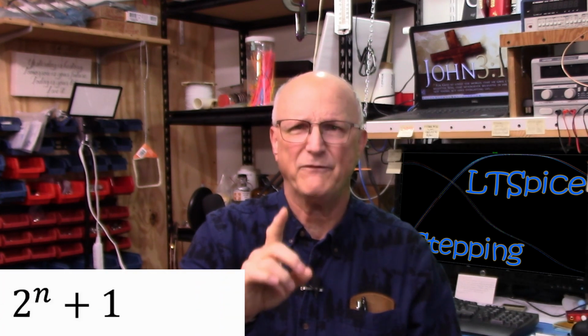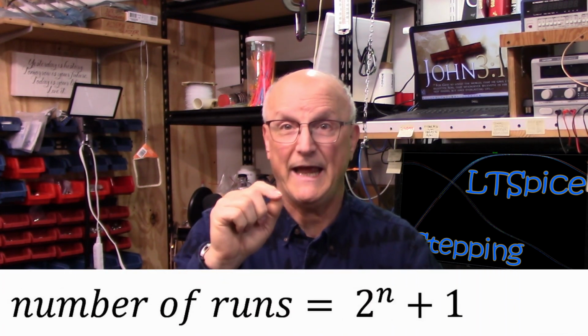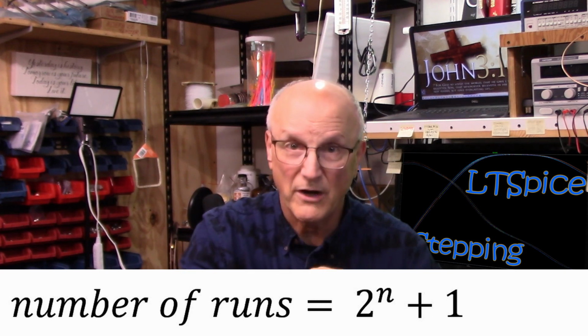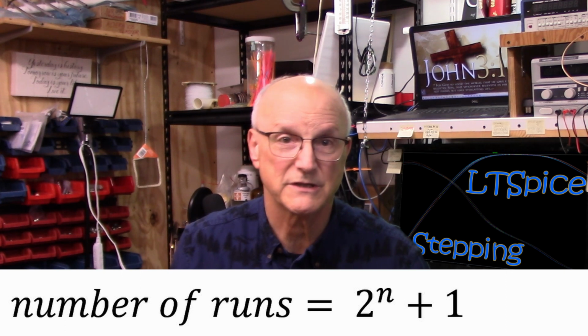The last couple of PSpice directives that we have to define set up the stepping parameters for our simulation. Well, now I have to bring back to your memory that we have 7 components that we're going to be stepping. Also remember that the number of runs that have to be made is equal to 2 brought to the nth power plus 1, where n is the number of components that you've chosen to step.